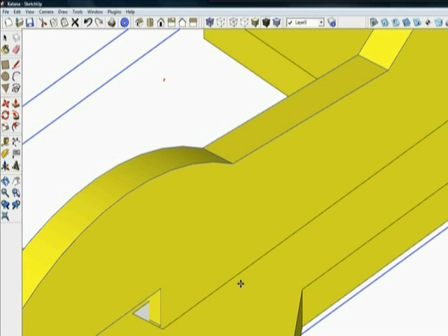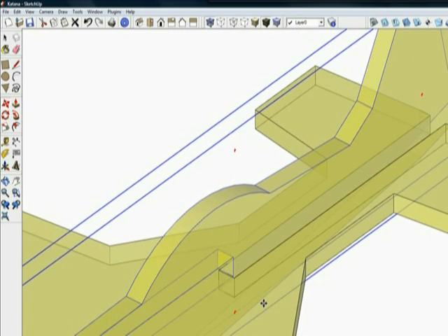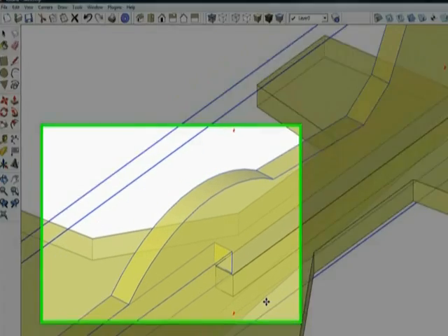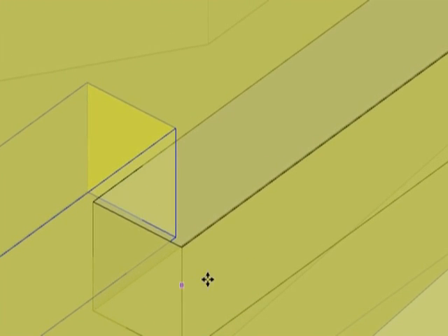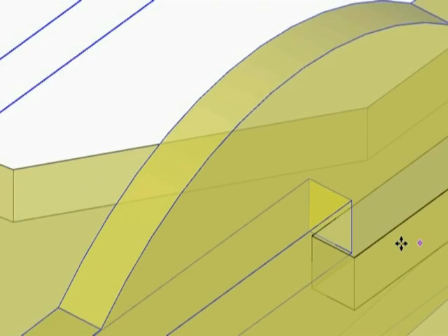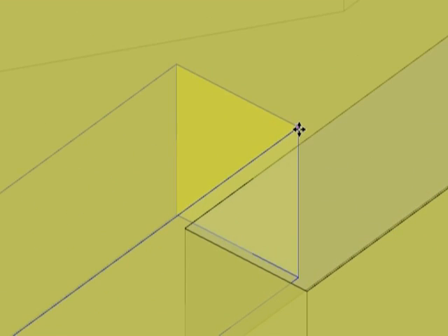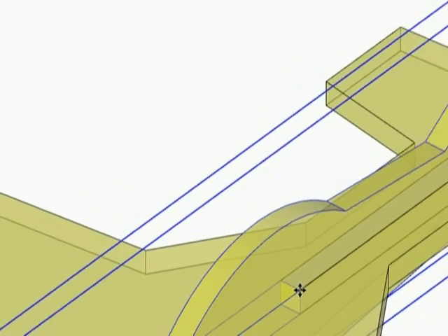There's another way of doing this that helps considerably. I showed you our views here, we can go into our wireframe mode. Now you got to watch out, because if you have a lot of lines going on, sometimes it's kind of hard to make things happen right. It confuses the noggin. My highlight is my part moving, so I should be able to select this and maybe now lock it in. Look at that. And it locked right in place.